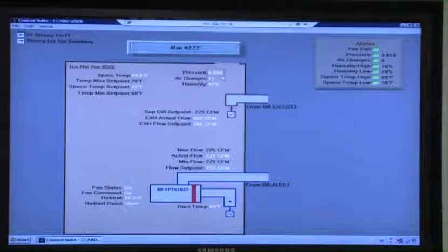Pressure 0. They must have the door open. Don't we have door contact closures on this? It disables the alarm if the door is open. Does this tell me anything? Can I get that on the screen to tell me that the door's open? Sure. Yeah, why don't we do that? If it's in a disabled mode, that means the door's open. We should have a door open. If it closes, door closed. So if you look at it and it's open, you're not gonna see pressure. If it says closed, we should see something there. We should see a relationship there.